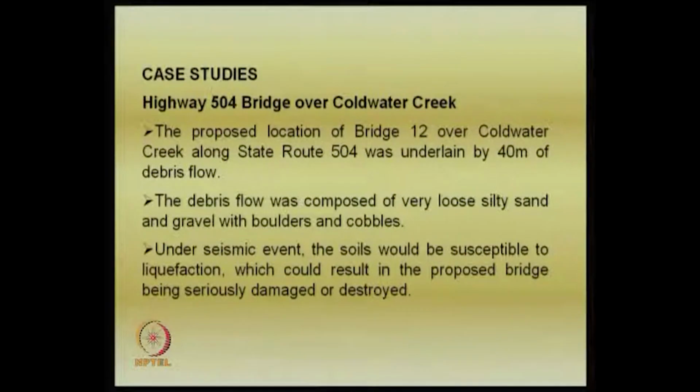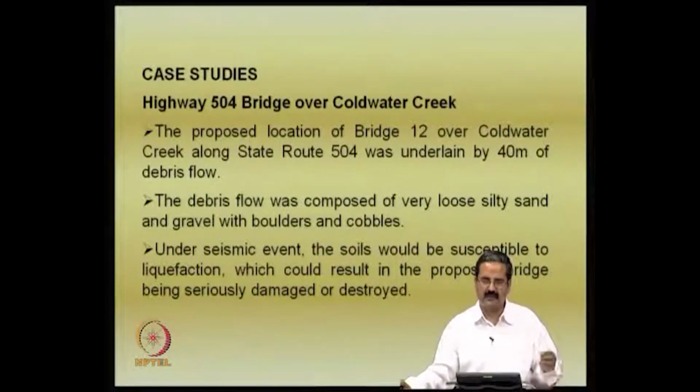There are stone columns, there are so many techniques that we did, and underwater there are some methods and all that. So, in this case, if we are looking for a very cost effective technique, and if you can achieve it by any of these means, it is nice. You can use either, for example, in a given situation, a dynamic compaction method, or you can use densification by blasting. You can just do whichever is cheaper and convenient, right, because it needs a lot of equipment. There are many issues involved in both techniques.